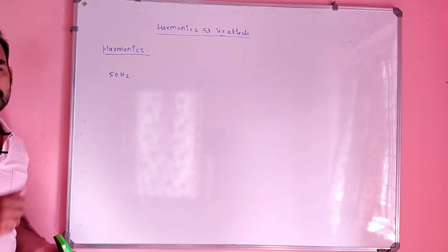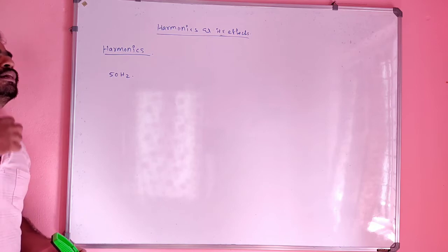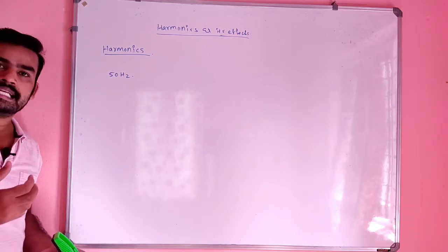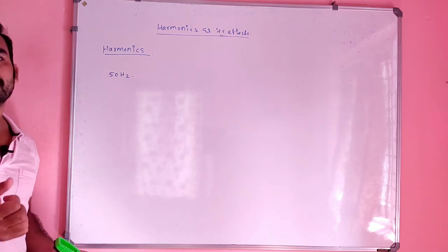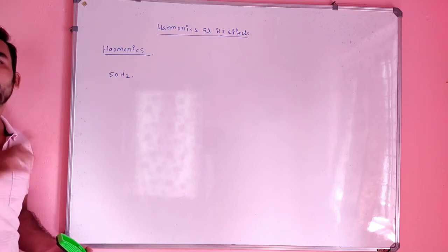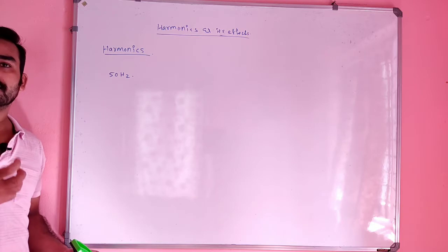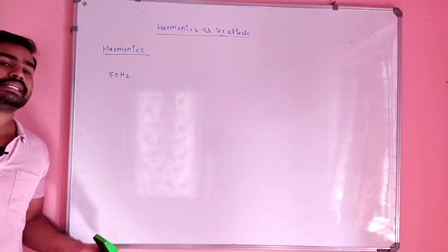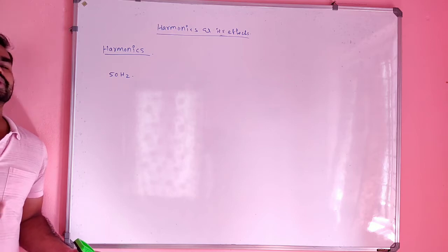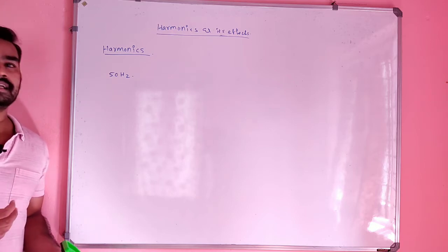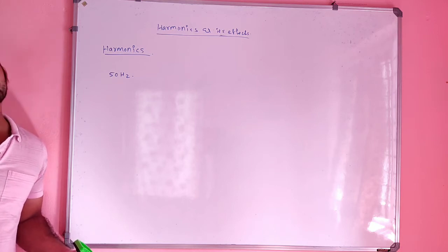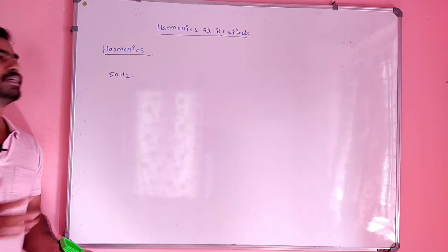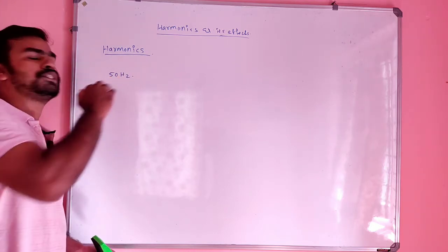But due to many reasons, maybe winding imperfection, or troubles in the power system, due to continuous switching operation and continuous on and off of large induction motors or transformers, or sometimes lightning, there is a possibility of producing some waves which are not good for us, which are multiples of the fundamental frequency.